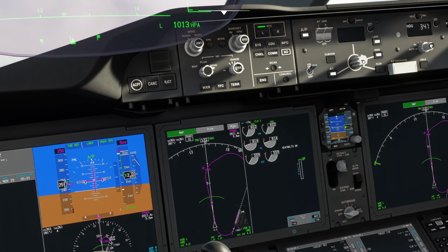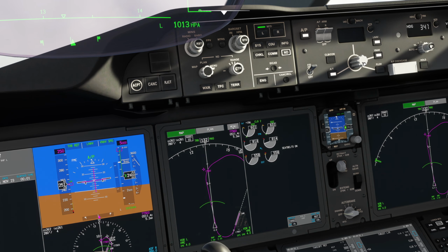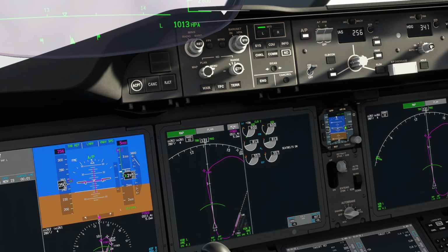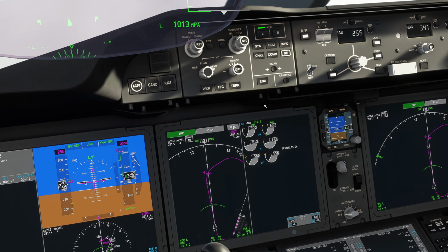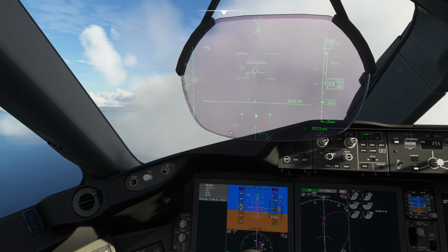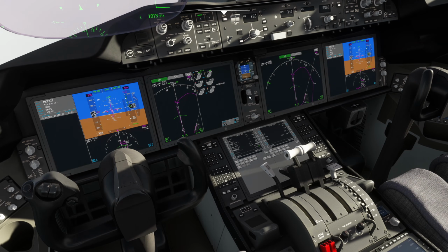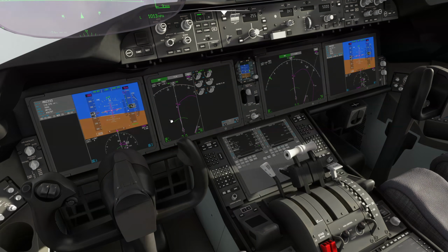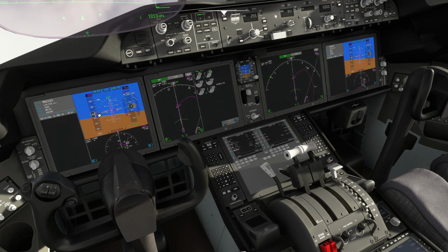That's because we are, like I say, quite a quick aeroplane. So what I'm going to do is open the speed window and just set it to the up speed. There we go, to make sure we don't get slow. And we're now climbing away. The flaps are up, the gear is up, and we are underway, climbing away, clean.